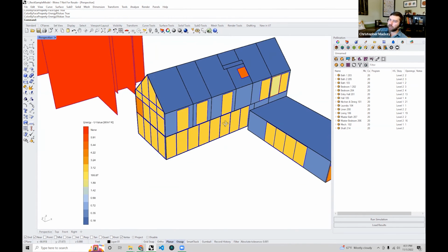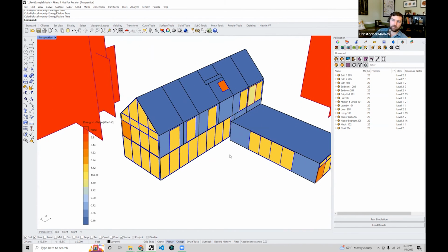So granted, I realize this is a naming convention that we kind of decided in Ladybug Tools and Pollination that isn't necessarily universal, but when we say U value, what we're basically referring to is the actual multiplicative inverse of the R value. This means that there are no air films at all in the calculation of U value.